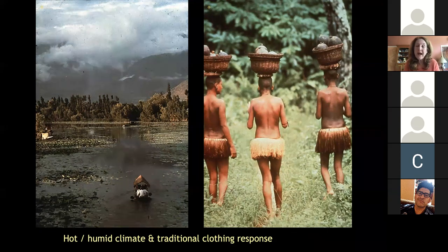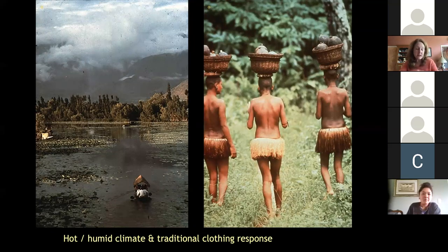Well, if you already have a humid climate where the air is already saturated, you're not going to be able to evaporate the moisture from your skin very readily, right? So you're going to need a lot of air movement past your skin to strip away those saturated molecules right next to the skin and increase convective loss by blowing more air. Remember we did that exercise? Strip away the moist, saturated air next to the skin so that the perspiration can evaporate.